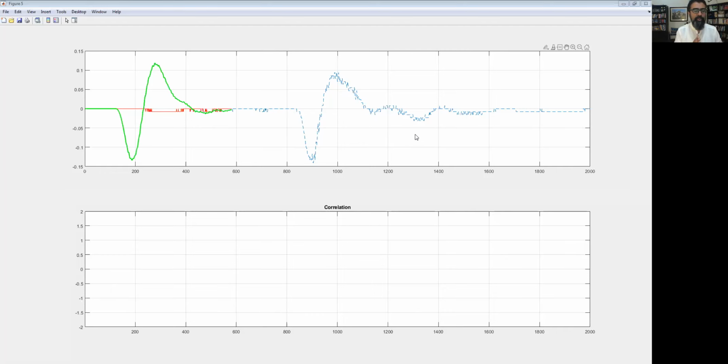And then what we do is we do correlation. So we compute the correlation here, okay, and then we start moving the template. So my MATLAB is okay. So you start moving the template to the right, and you keep on computing the correlation. And you see the correlation stays quite low as you're sliding over the signal in which you did not have a gunshot and there was silence. Okay, it stays low, stays low, and as you inch towards where the gunshot was, you see the correlation starts rising, right?